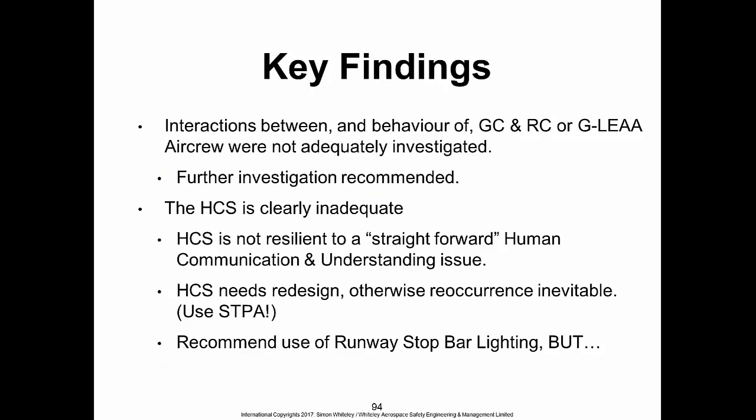So the key findings: interactions between and behaviour of the ground controller, the runway controller, or the GLEA aircrew were not adequately investigated, or they weren't reported, just to be clear. So further investigation is recommended. The HCS is clearly inadequate. The control structure is not resilient to a straightforward human communication and understanding issue. The HCS needs redesign, otherwise reoccurrence is inevitable, and you could use the STPA process to do that. And I recommend the use of runway stop bar lighting.